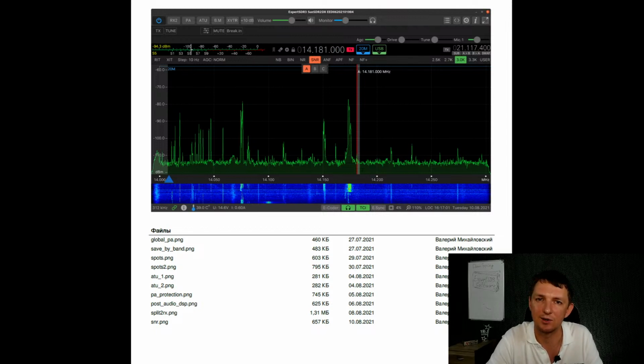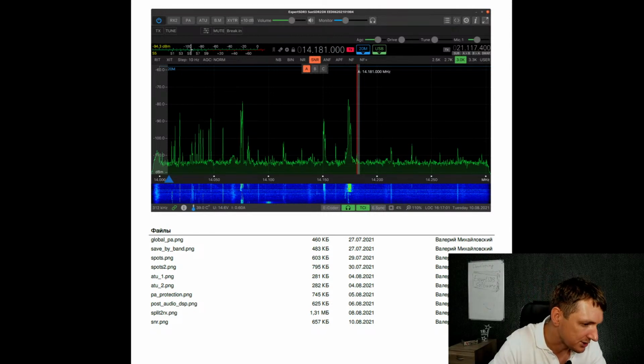And our schematic is based on receiving in just one Nyquist zone. When you work in HF, all filters at the input between the antenna and the high-speed ADC will reject all signals from other bands higher than 65 megahertz. And I think I've answered your questions.